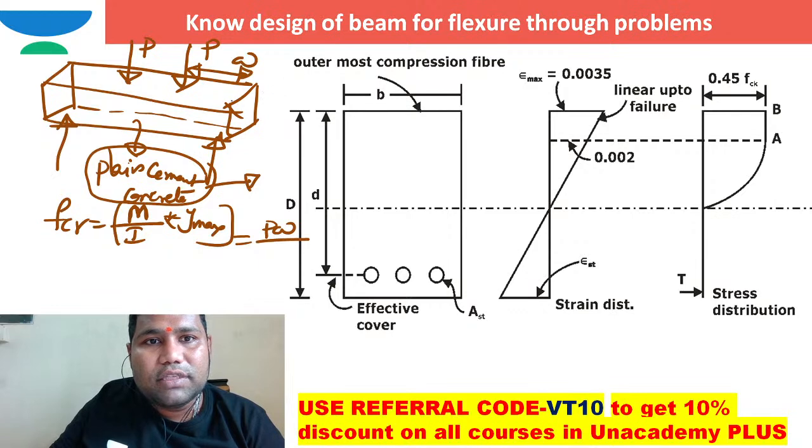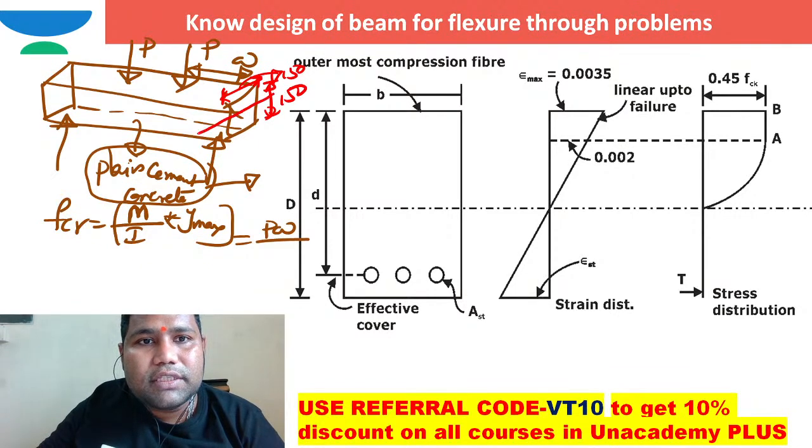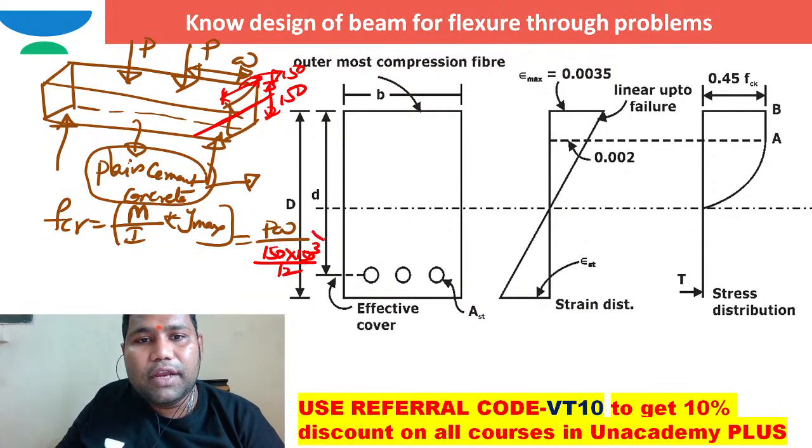We can work out I: this is 150, this is also 150. About this axis only bending is happening. So I is BD cube by 12, and Y max, the maximum fiber distance, is 150 by 2, right?